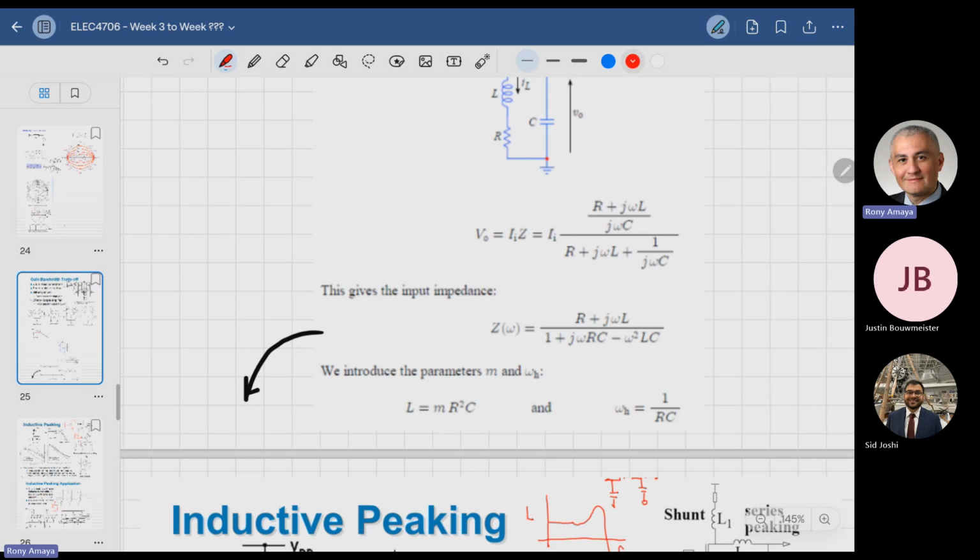Yes. The Cherry-Hooper is setting up these currents that you can use to tune the gain and bandwidth. There's always a trade-off in there too, like if you're going to increase the gain. Yeah. So the question is, why do I need to have gain bandwidth control? Isn't the goal to always have the highest gain and the highest bandwidth? Not necessarily. And the reason for that is, okay, that's an excellent question.